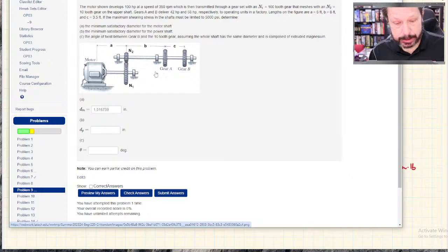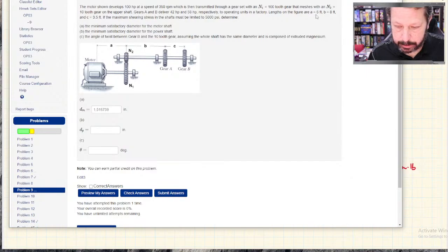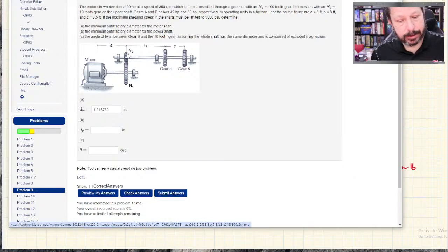In the picture here, the big gear is the one that's driving the smaller one. It's connected to the motor. The smaller one is being driven by the big gear, so that smaller one is having to spin around multiple times faster. Whatever N2 to N1 is, 100 to 10, so it's 10 times faster. So it's sped up, but it has divided the torque. Whatever torque N1 was delivering is divided by 10 in this case. But it's sped up a lot.